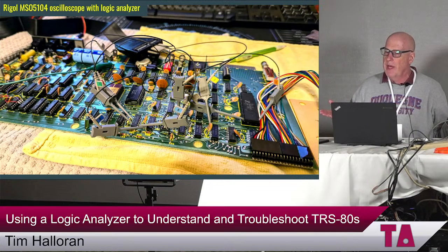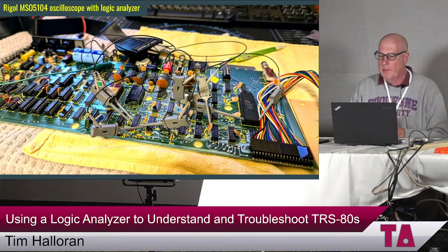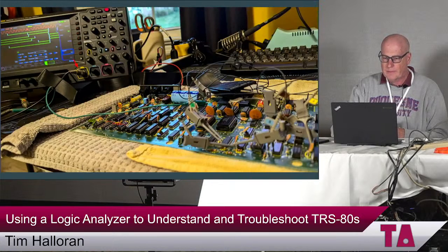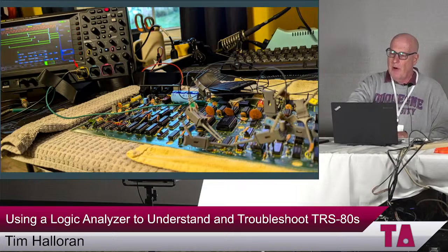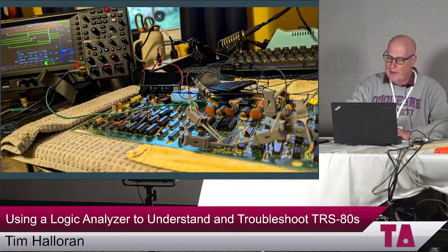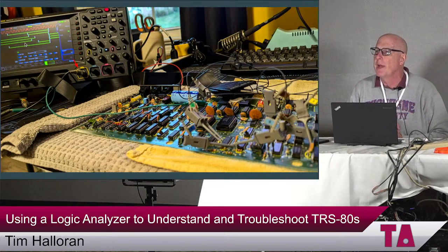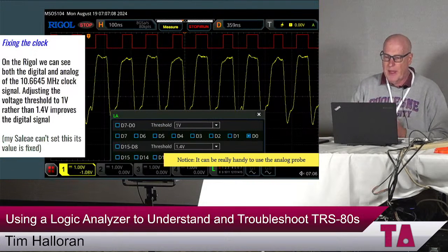So the Rigol I mentioned, the Rigol MSO 5104 scope, has a logic analyzer. So we're actually going to use that, not the oscilloscope probes. Again, this is what it looks like. I've hooked up the Rigol to the motherboard, and here's what you end up with in this particular case on your desk. You have all the signals going into the same place the SAILI was. I've got this block that runs a ribbon cable into the oscilloscope, and we manage things on the oscilloscope, not a PC laptop. So that's kind of different.